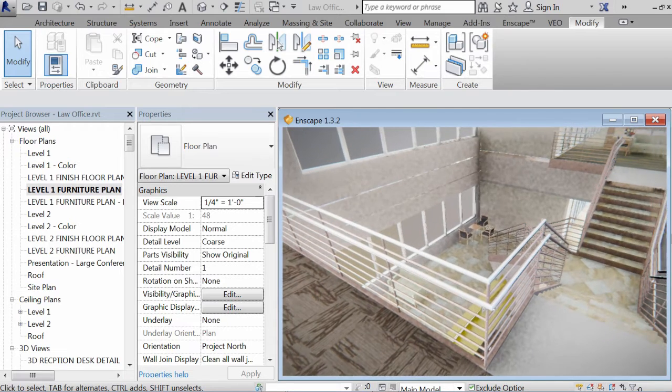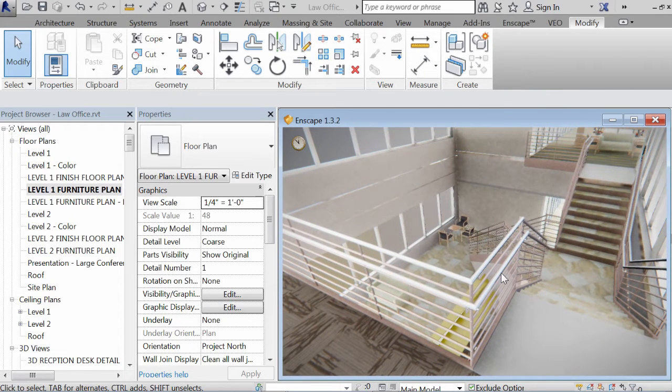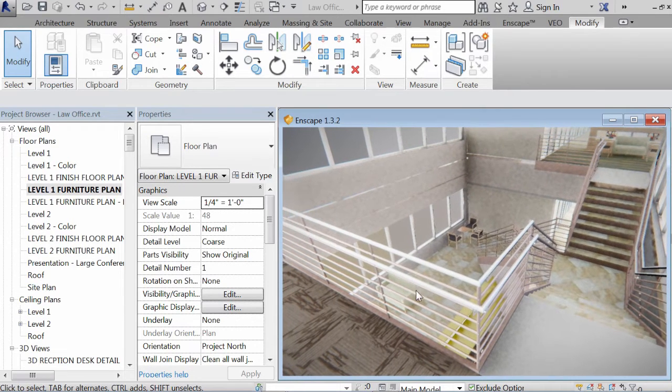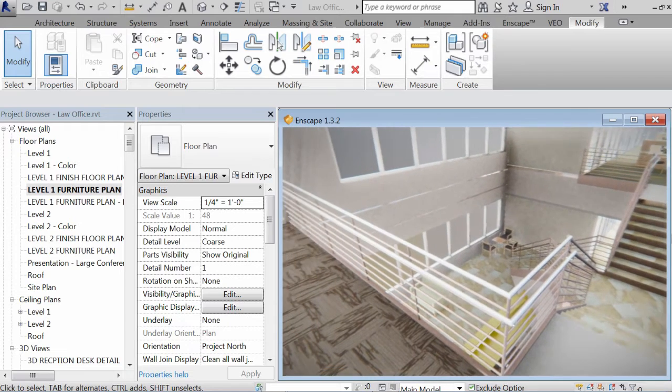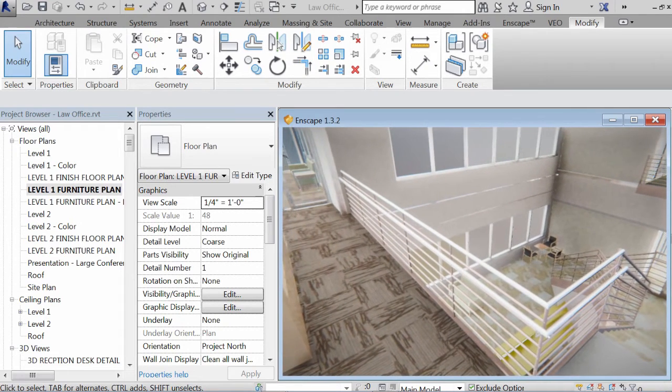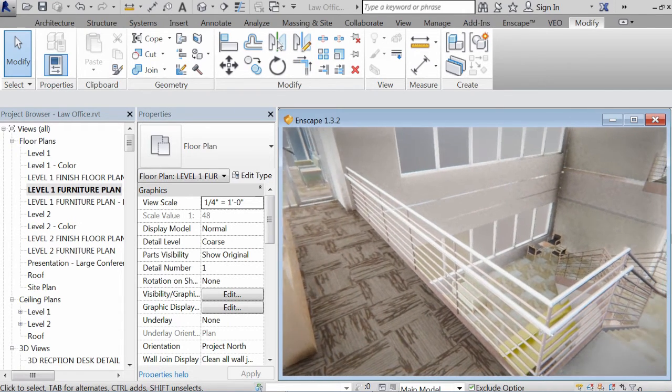And actually, if you look here, the handrail that's at the edge of the floor actually has an extra rail added that mimics the stringer at the bottom that then lines up with the stringer of the stair. So this structure is contiguous here. Yeah, okay. But it's really part of a separate railing family rather than the railing that's sitting on the actual stringer of the stair.